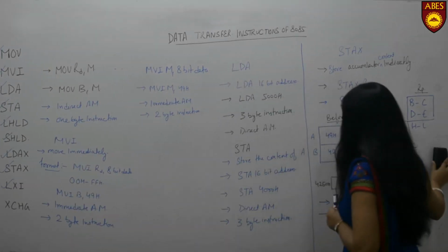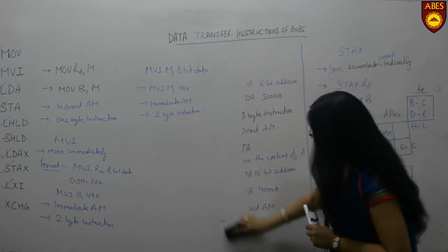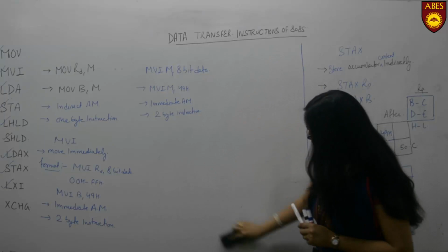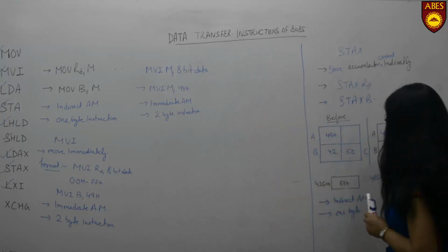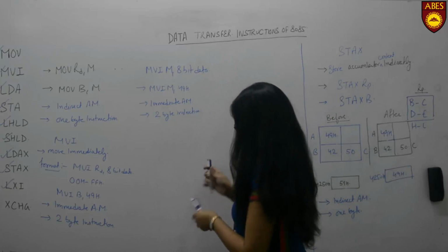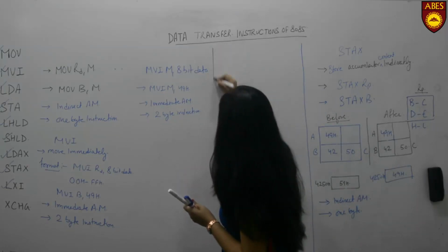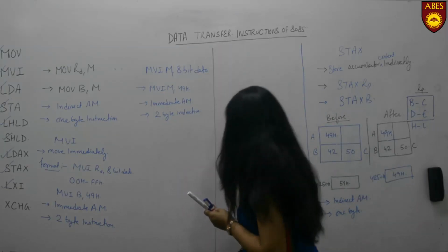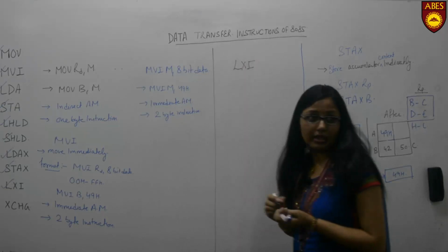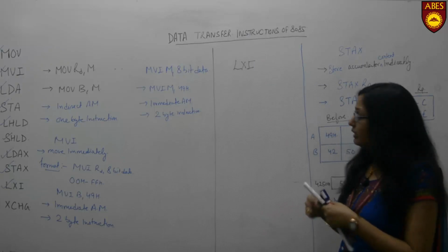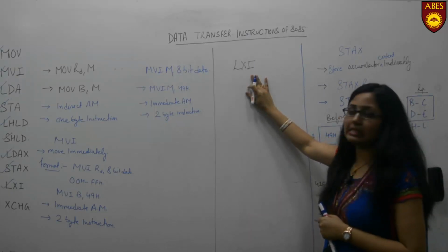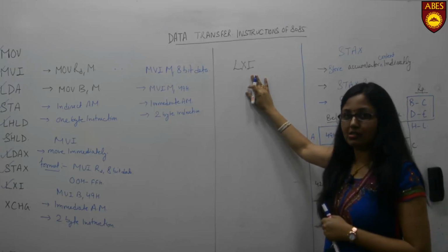Now the next data transfer instruction is LXI. What is this LXI? LXI instruction is used to load immediately 16-bit data into a register pair.